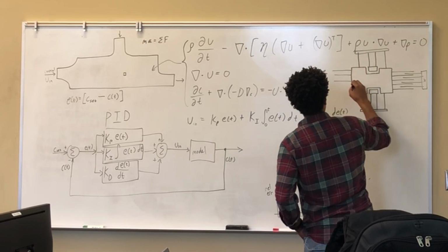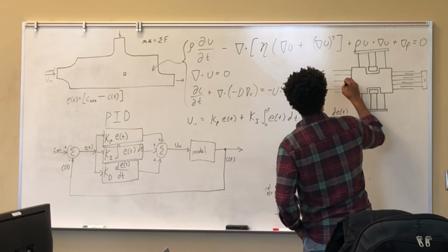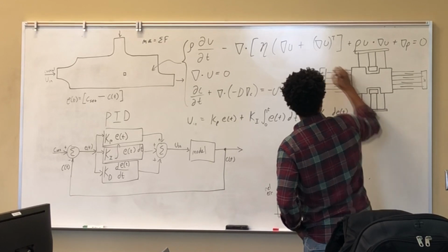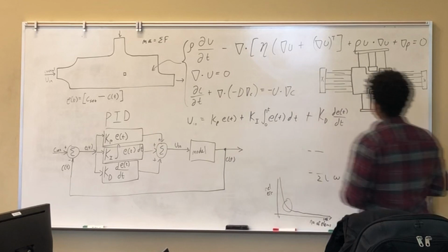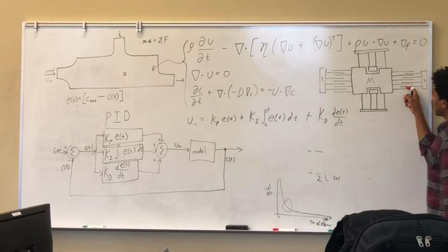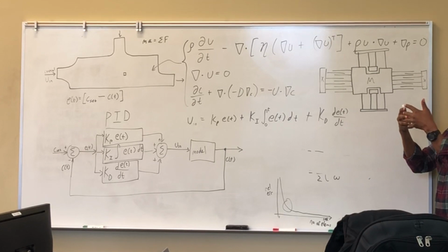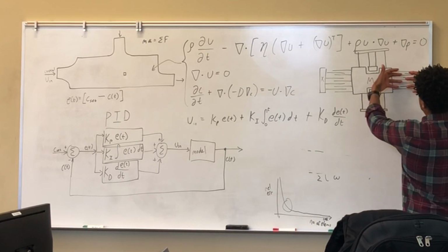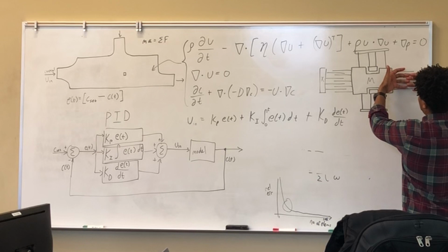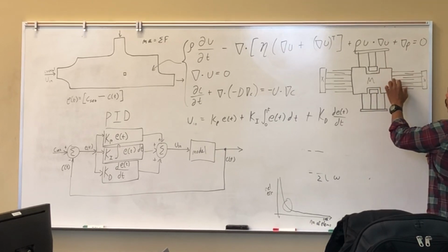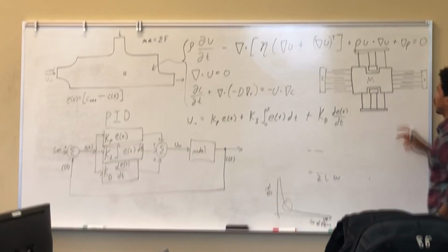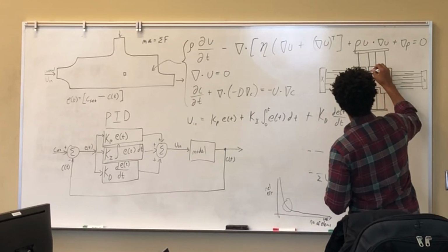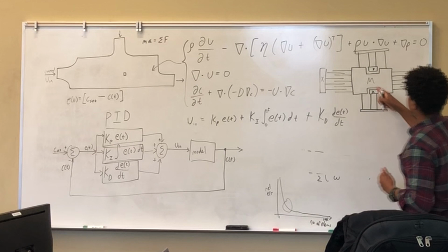And so what we'll do is demonstrate that the force that these variable capacitors apply onto this proof mass here is actually independent of the overlap of the comb drive. Okay, so this part right here is going to move back and forth. This right here is like a stator, and it moves back and forth like this. But regardless of what the engagement is, the force on these comb drives is going to be identical. It all depends on your voltage, and it's proportional to the voltage squared. So this is anchored. That's anchored too. So everything with the x's are anchored.